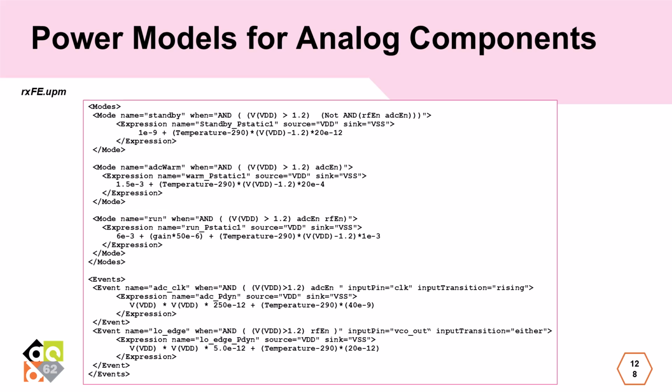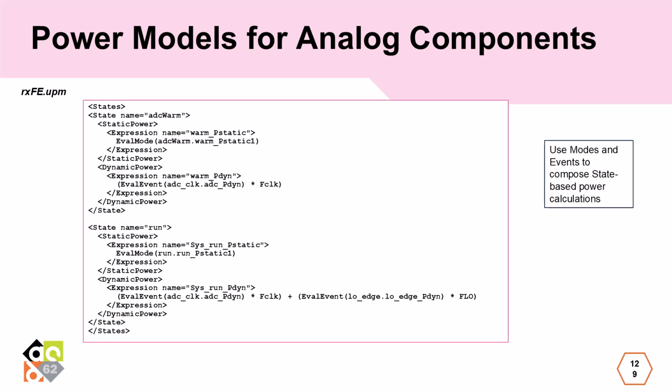In addition, we have a couple of event-dependent energy consumptions, including the A-to-D converter when it takes a sample, and the mixer when it gets hit by an edge of its LO input. And then for state-based analysis, which is what PowerCalc is going to use depending on its scenario file input, we use eval mode and eval event to compile power numbers for those various states.